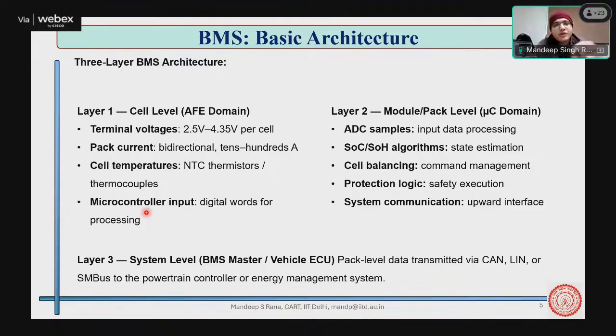So if you come down to the block level of the same PCB card, what you will observe is that there is one end which is actually the battery end, and there is another end which could be a big capacitor sitting here, and then there is a converter which feeds your motor in, let's say, an EV environment. Otherwise it could be some other situation, like a supply coming in and a charger sitting there which communicates to the HV side.